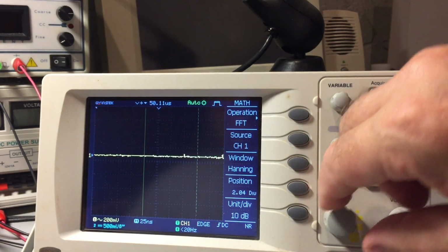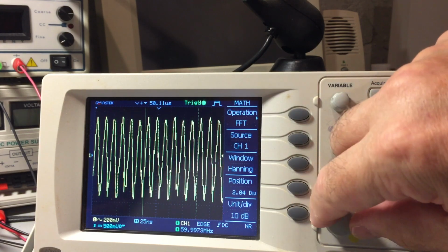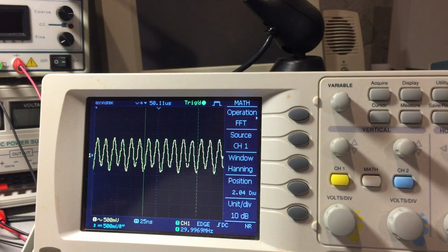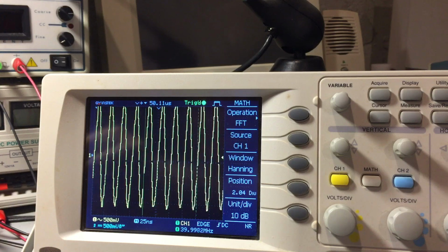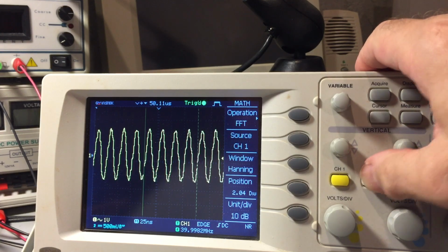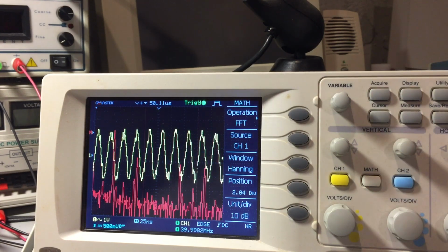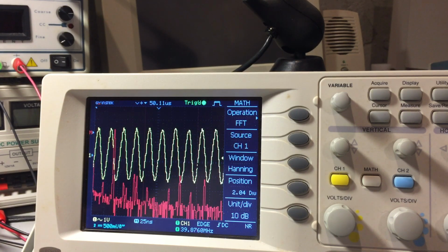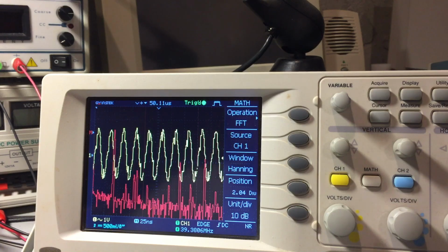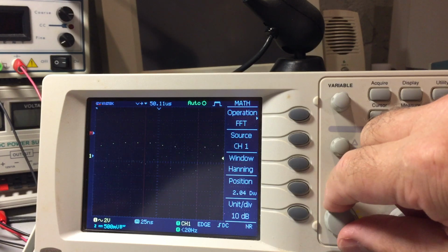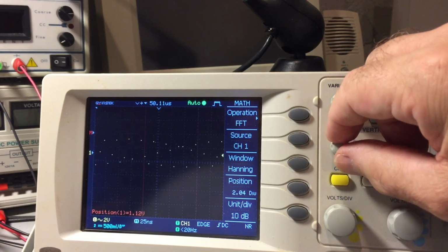Let's go ahead. That's back down to 30 megahertz. And we can take a look at the spectral components here. So let's look at the FFT real quick. Again, this is the fast Fourier transformation mode of the scope. It changes the scope from the time domain to the frequency domain. So let's change the volts per division and some adjustments here. Bear with me.